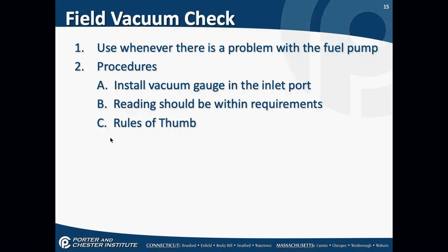if my pump tests out okay, so let's say I get my 10 inches of vacuum with just checking the pump, what's going to be my next step? And this is okay to guess. It's okay to be wrong. What is my next step with my vacuum gauge installed on the pump? What am I going to check next? Check the outlet.